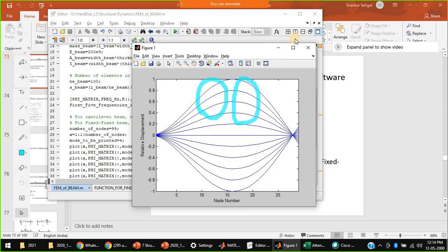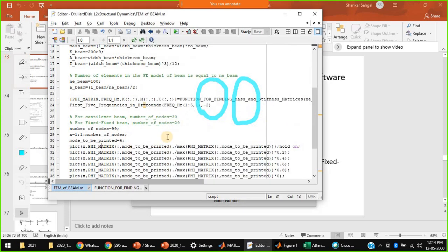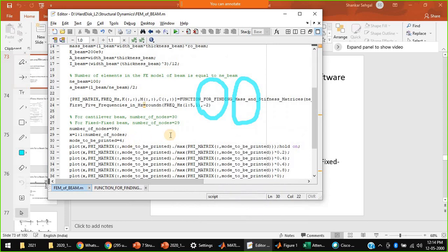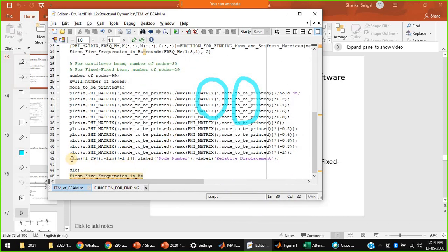Okay, here the x-axis is not coming properly. Let me press F5 now. Actually the x-axis has been limited to show the variation between 0 to 30, I think. So that setting needs to be corrected. Here I am converting this line of the program into a comment by pressing Ctrl R. You can see the x limited value is decided in this particular line of the program. Now let's press F5.